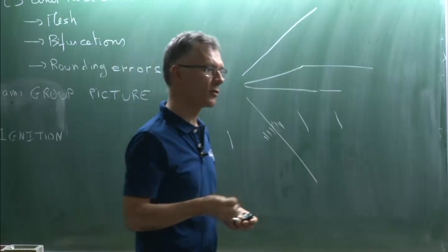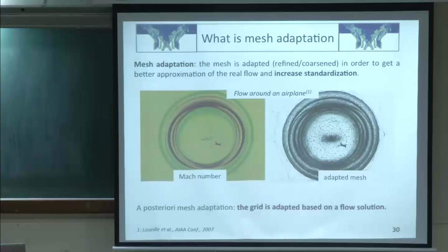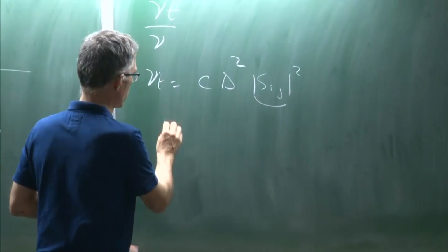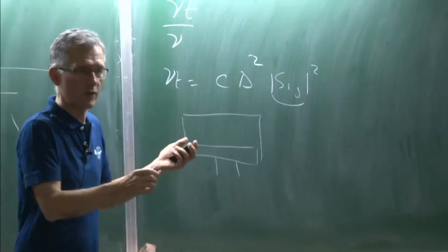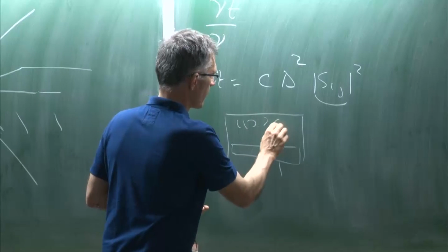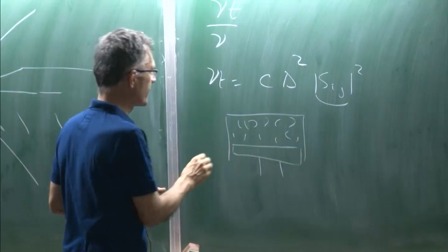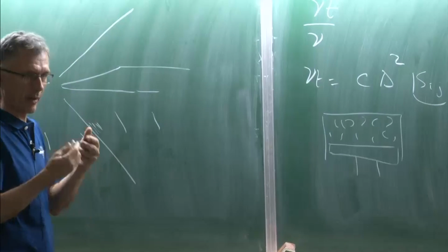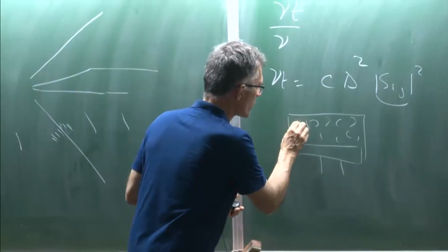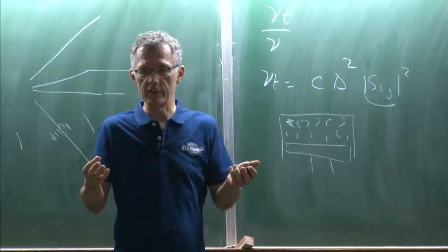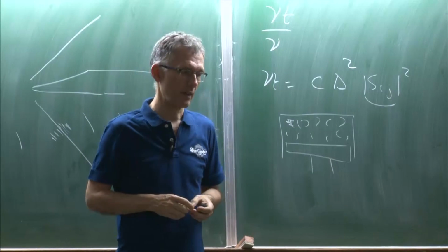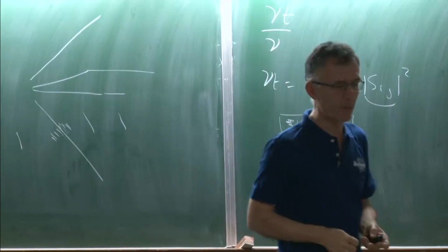The main problem when you go to LES is that you're going to need to put points where vortices are, but there are vortices everywhere. In a turbulent flow, in a combustion chamber, you take a piston engine, for example, there is vorticity everywhere. So you cannot really say as easily as here, my mesh refinement system needs to put points here. Everywhere where there is turbulent activity, you should put points. So how do you decide? This is where things become complicated.